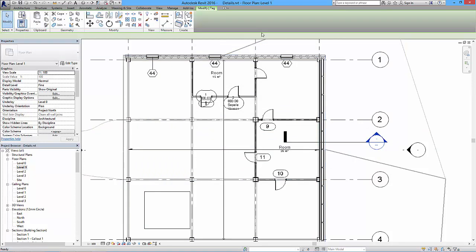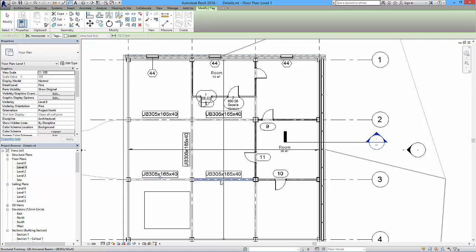And then if I tag by category, now it's looking for floors at the moment because that's the dominant one. I can't see sort of underneath it until I tab in. And then if I tab to that, it's going to give me the type of beam that we're looking at. Okay, so once it's picked up a couple, then you're good to go.